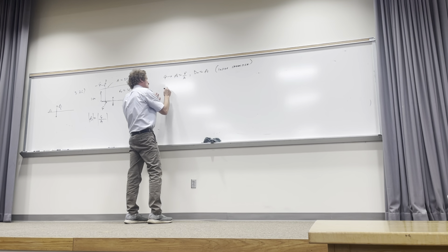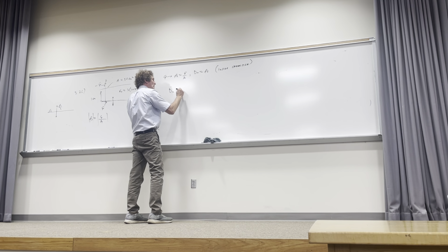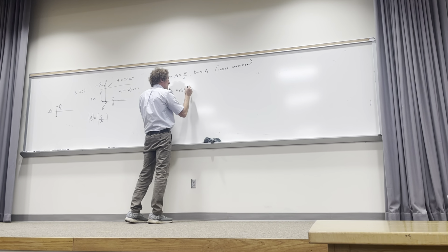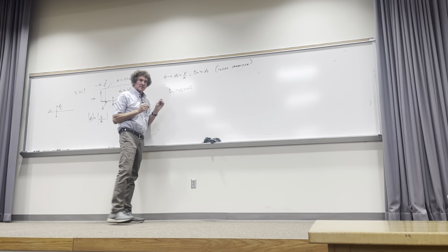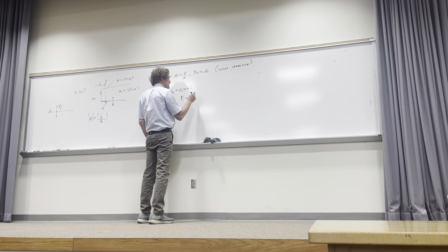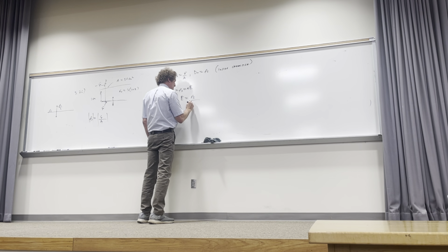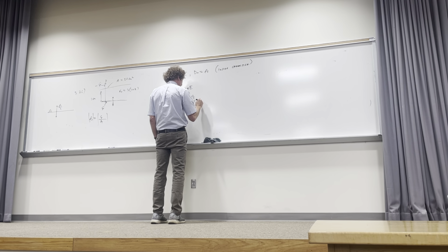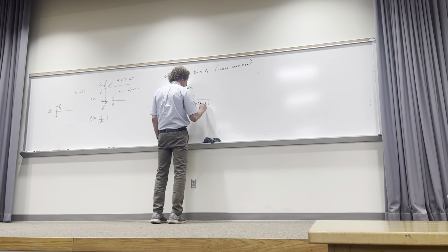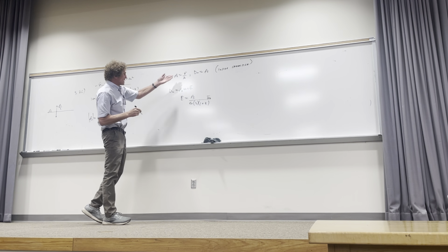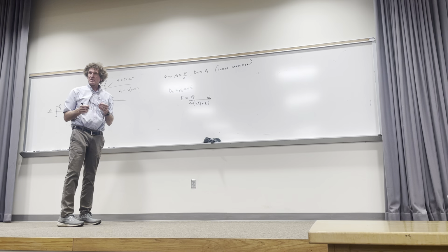Now, once you have the D field, D normal equal to rho s, you also know the D field is the E field times epsilon, correct, class? Therefore, you can get the E field and say it's equal to rho s, and I'm just going to leave it as rho s for this part, over epsilon naught epsilon r. And that's epsilon r there, which is 3 times 1 plus z. And it would be in the az direction. Now, we know rho s is Q over A, but Q is an assumed value. We're just going to leave it like that, okay?